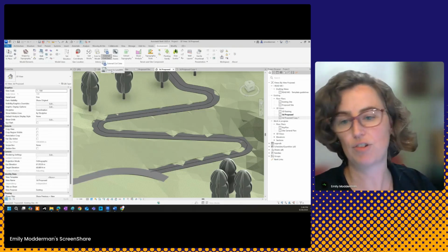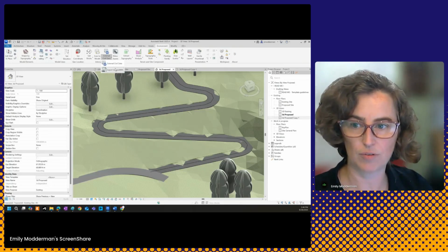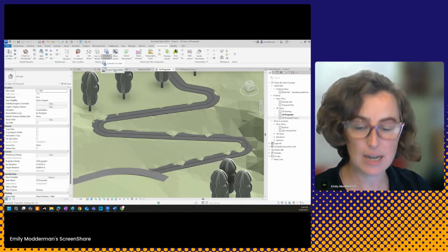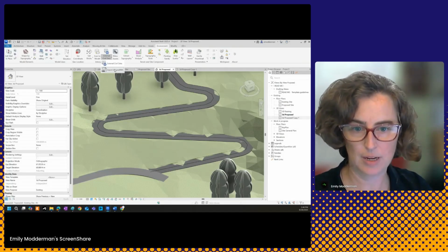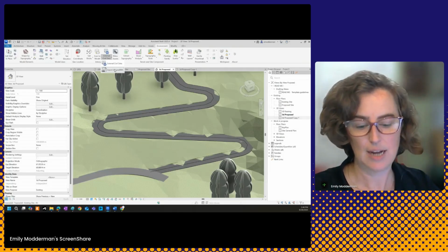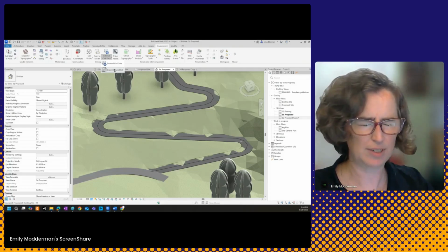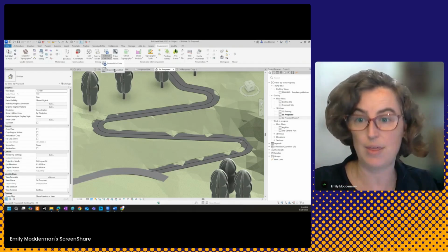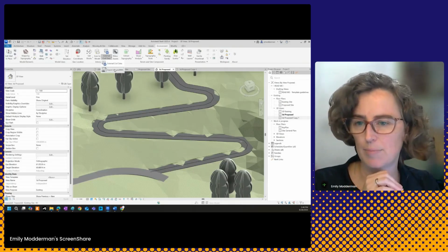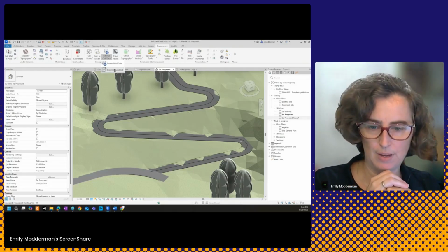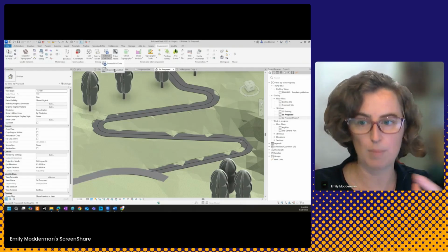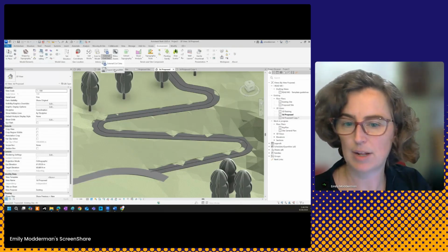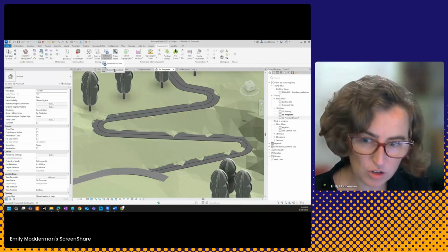If I make major changes to this topo surface, I can export this to LandXML. You can bring that into your civil file, and it will create a surface. I believe you can merge, let's say, your existing and a landscape proposed, and then you have that combination surface. So LandXML is the gateway between the two systems.